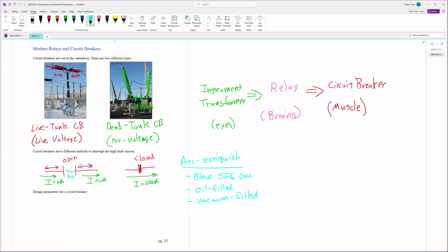Okay. Whenever you're buying a circuit breaker from a manufacturer, there's a couple of things you need to figure out. So let's kind of draw the actual circuit breaker itself. So typically they're squares like this. I said square means circuit breaker, so we're going to go with it. Okay, there's 2 major things that you need to figure out. One is your fault current or your interrupting current. How much current can this interrupt? Typically, let's say 20 kiloamps, right? That's one rating. How much it can interrupt.